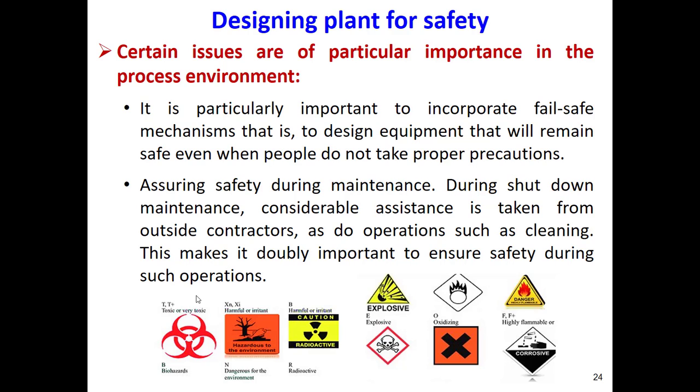Okay, so you might hear this term, fail safe. A fail safe mechanism means the equipment has been designed in such a way that even if it fails, the process will still be safe and the equipment will still be safe. As I said, examples of how we can ensure a fail safe mechanism are designing some switch, emergency valve, or pressure relief system. These systems all help us reach such a mechanism.